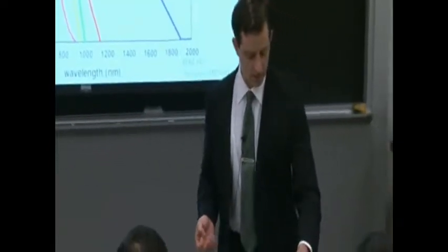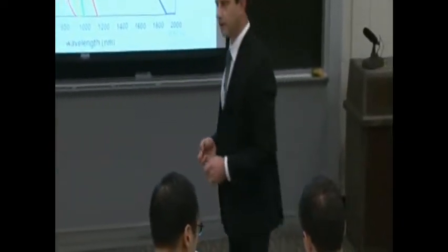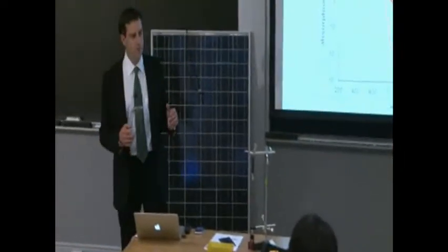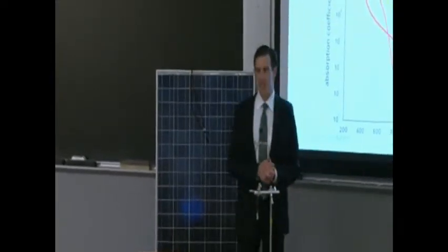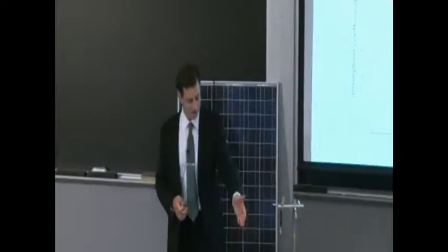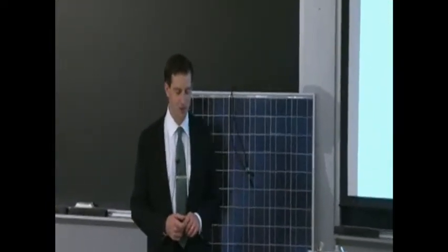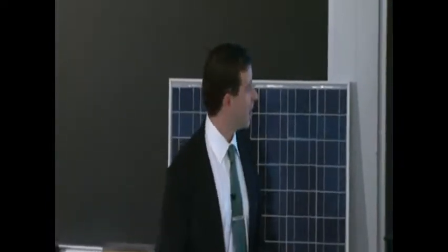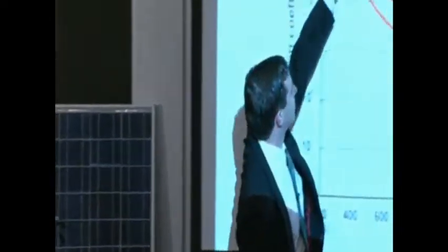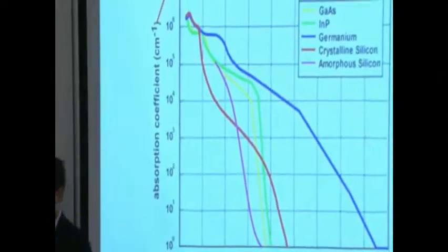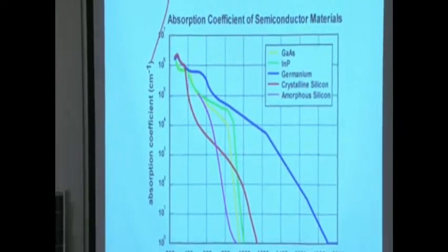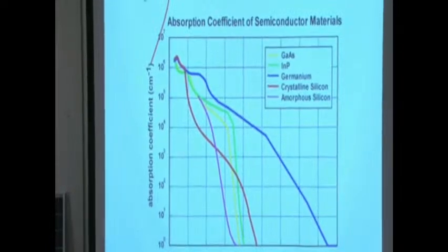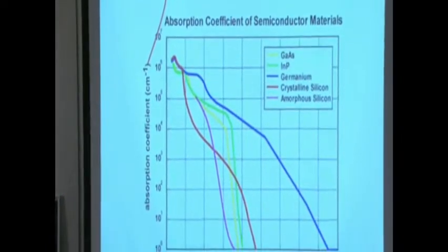But you can see here that if you look at the thickness of these materials inside of that little bin, these are small shards of silicon solar cell wafers. Their thickness is on the order of 100 microns. Those are particularly thin. You have other solar cells where 170 microns is a typical thickness for silicon. And for gallium arsenide, you can deposit thin films that are on the order of a micron thick, or less. You can go down to a few hundreds of nanometers and still make, actually the record efficiency gallium arsenide solar cell is a few hundred nanometers thick.